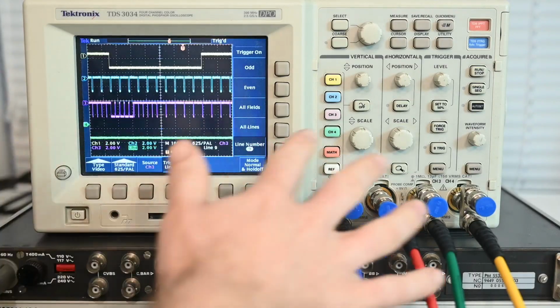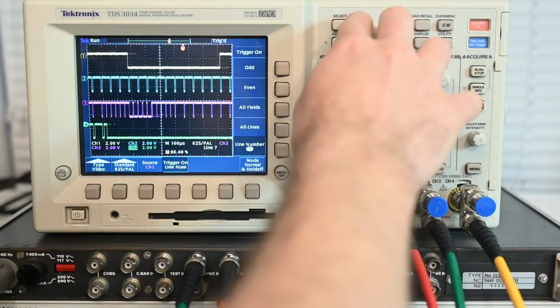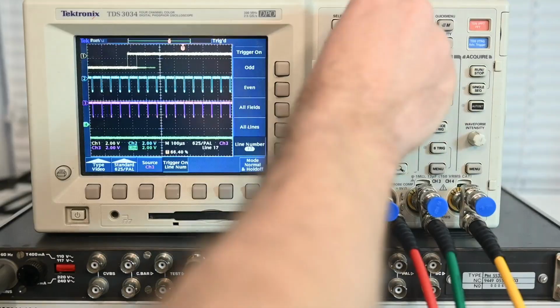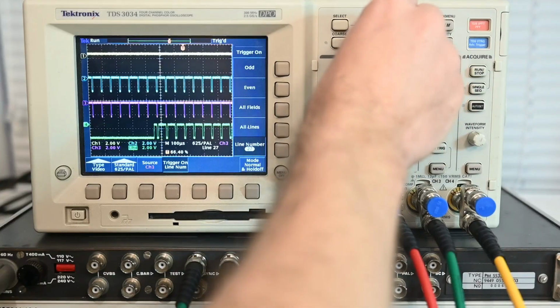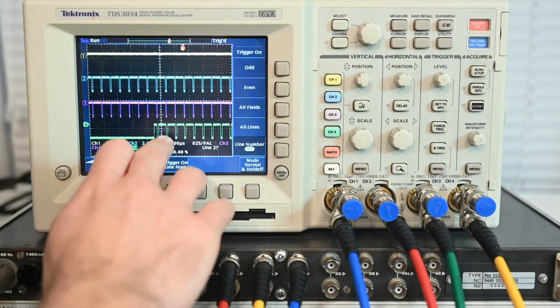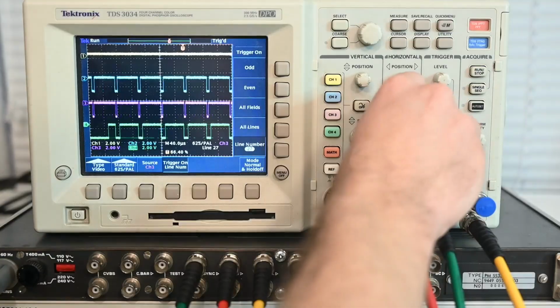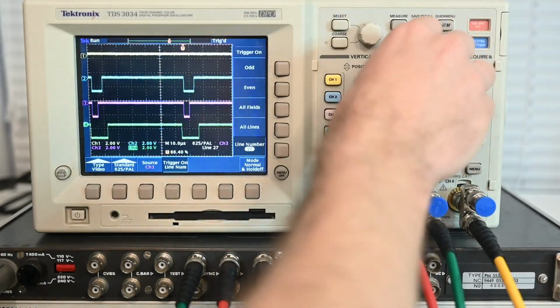Next, if we turn on channel number 4, this is the mixed blanking signal. Now to actually see what's going on here, we have to progress through the field a little bit. If we scroll over to here, down to about line 26, we can see that the polarity of this changes. So we start to see that it goes high momentarily. So if we just zoom in on that, we can see what's actually happening here.